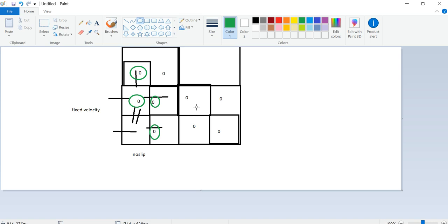That's okay. If the velocity here is 0, and then the velocity here is 0, one of these must change, because if there's flow coming in here, flow's got to be going out here somewhere. But if this is a no slip, then maybe you can't quite change this velocity, because the condition over here is a no slip condition, which means the bottom is like a stationary kind of thing. So OpenFOAM is stuck and says, okay, maybe this speed cannot be that high, so I need to increase my velocity here and here.